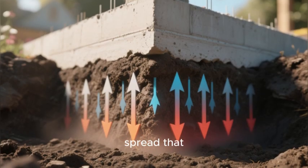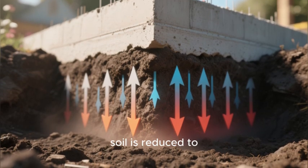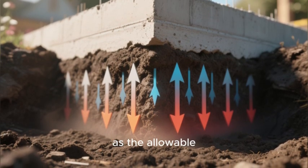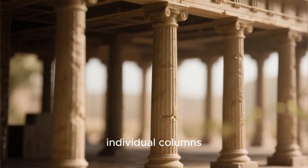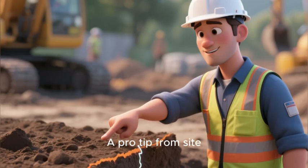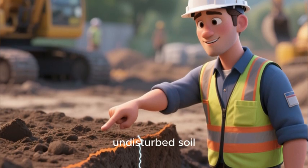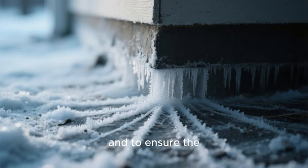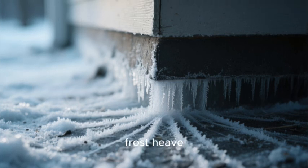Its job is to spread that concentrated load over a large enough area so that the pressure on the soil is reduced to a safe level, known as the allowable bearing capacity. You'll see these under the individual columns of a framed structure. A pro tip from site engineers is to always pour the footings on undisturbed soil, never on backfill, and to ensure the bottom of the footing is below the local frost line to prevent frost heave.